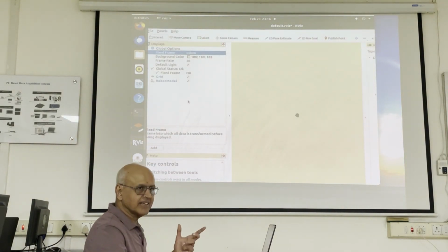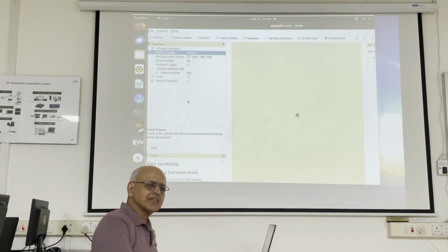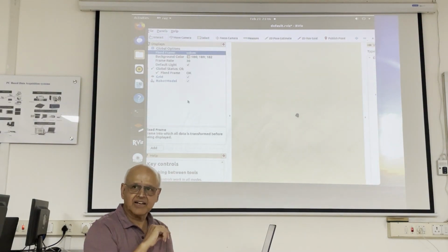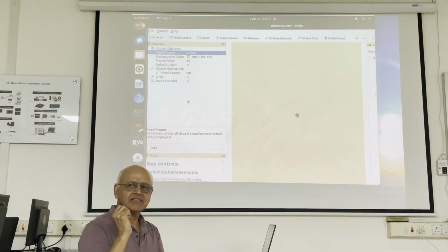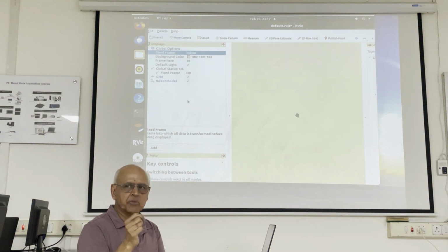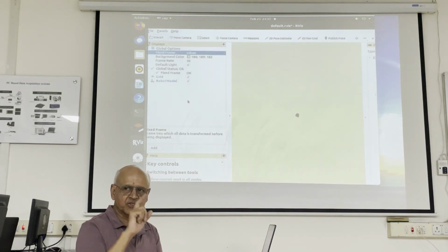So I want to see. The TurtleBot 3 has a LiDAR on it. LiDAR throws out a laser beam, picks up the return, and it can tell where the obstacle is fairly accurately. This TurtleBot 3 LiDAR is a 360-degree LiDAR with a spacing of 1 degree per ray, so 360 rays.